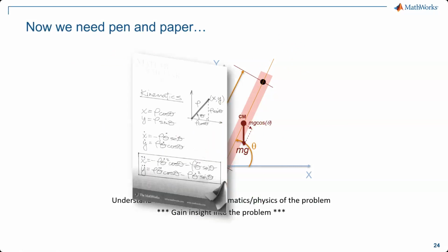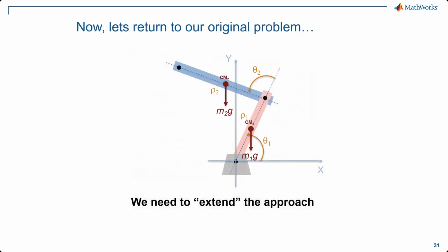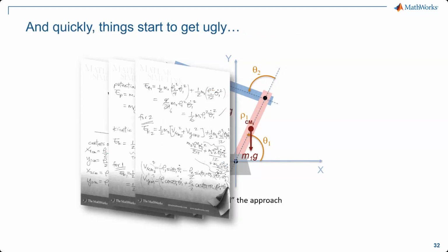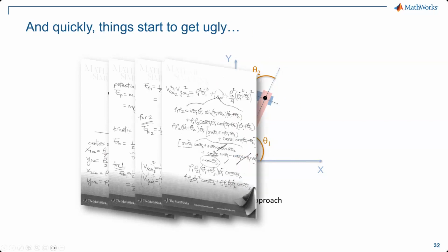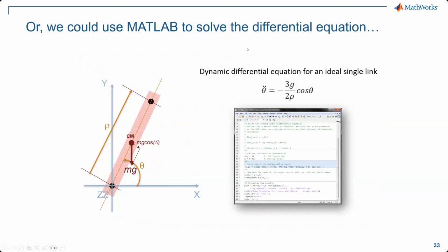And I can basically write the kinematic equation and the dynamic equation, and then again add another rod and do the same thing, and then again I'll do the same thing. I'll write the kinematic equation, and as the different pieces are coming together, this is also going to grow more. And when finally you have that equation with you, for example, for the case of a single rod, you can use MATLAB to model it.